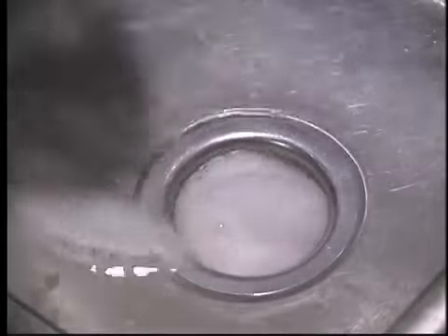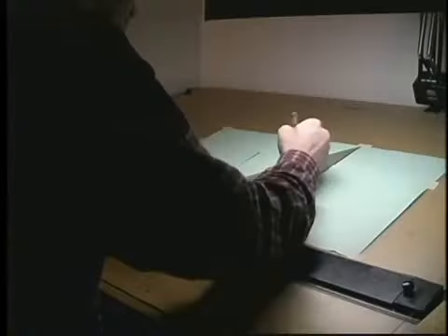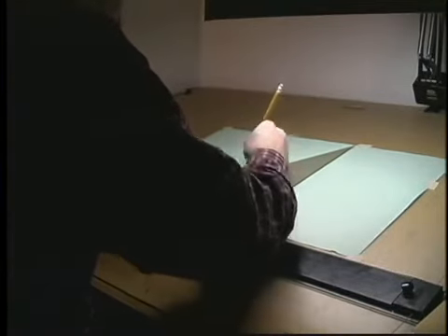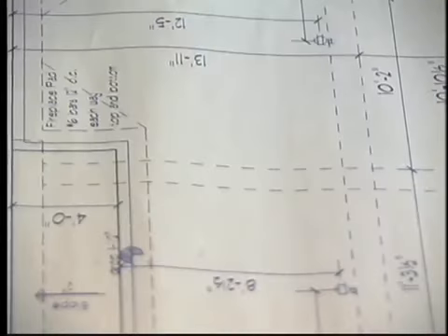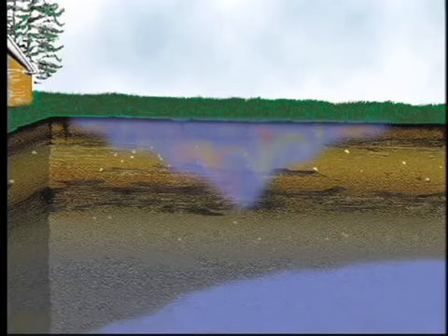Because of that, you have to carefully consider the amount and the type of wastewater generated. In other words, the land must be able to accept and treat the amount of wastewater you discharge. If the system is too small, problems can occur. An on-site system is designed for a specific amount of water based on the size, purpose, and average use of the facility.